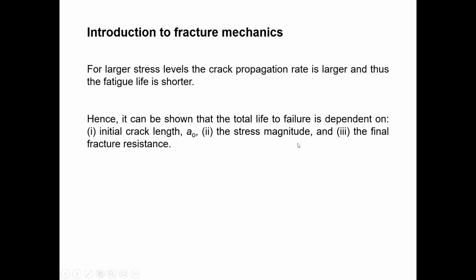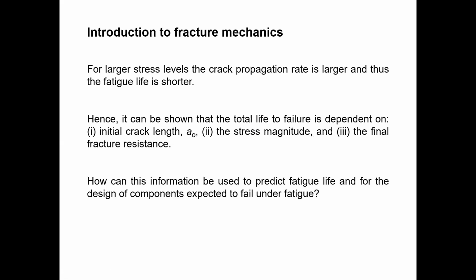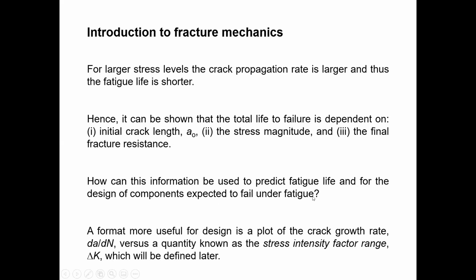So the initial crack length, stress magnitude and the final fracture resistance will govern the total fatigue life. I'm just reminding you of the last few lectures, where we discussed the main difference between total fatigue life and growth fatigue life, growth fatigue data and total fatigue data. So how can this information be used to predict fatigue life and for the design of components expected to fail under fatigue? That is the question.